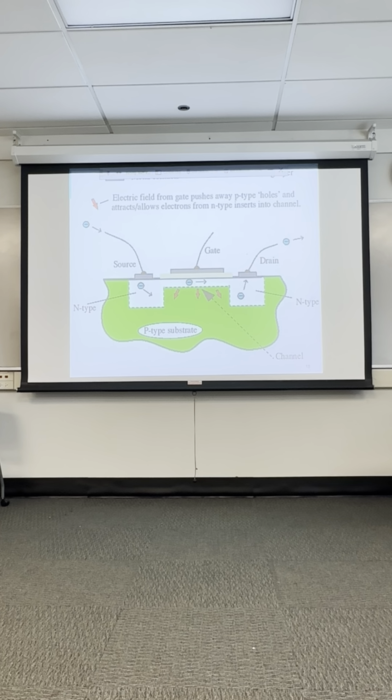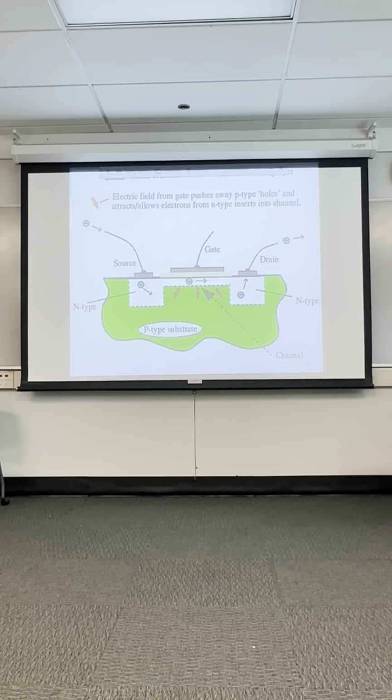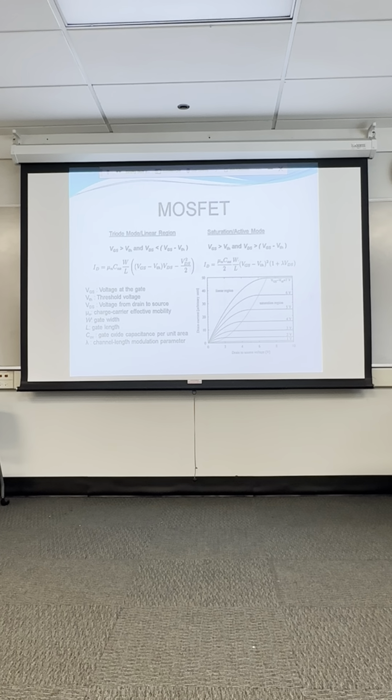But again, to actually design circuits with a MOSFET, the part we really want to understand is that if you do not have any gate voltage, there's no channel under the gate. In order to get this channel under the gate for current flow, we have to apply a gate voltage, and then we need to apply a drain to source voltage. So there's our positive gate voltage.